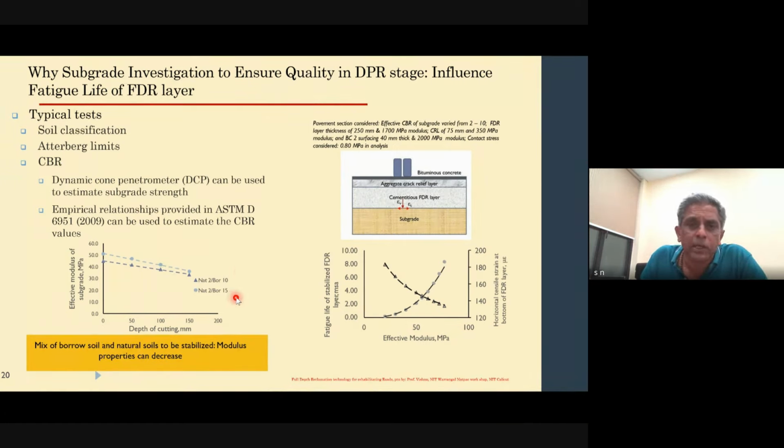So all of a sudden, the cement that you are adding is not going to be enough. Now, what happens because of that? Mixed properties, the strength, the durability, everything changes accordingly. You are going to have an inferior quality product at the end of the day. So the ultimate thing is that the gradation and the materials used must be consistent with what is being done as a part of the mixed design process.